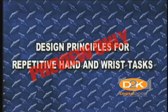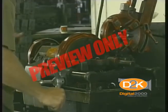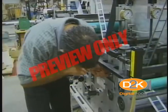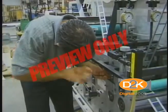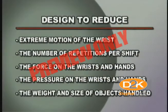It is important that repetitive hand and wrist tasks be carefully studied to implement ergonomic improvements. Hand and wrist problems account for a significant portion of work-related musculoskeletal disorders. Here are some ideas that may be useful in reducing trauma to the hand and wrists. Design to reduce extreme motion of the wrist, the number of repetitions per shift, the force on the wrist and hands, the pressure on the wrist and hands, and the weight and size of objects handled.